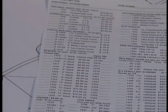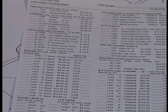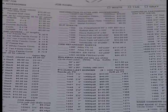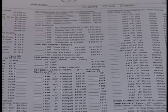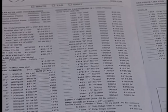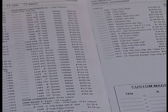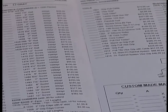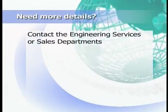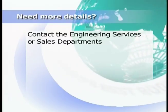The order blank also functions as your punch list. It addresses most situations that you will encounter on the rooftop during your survey, including two-way vents, stacks, drains, and accompanying CDR rings, tools, welders, fascia, drip edges, gravel stops, termination bar specifications, and other Duro-Last details, accessories, tools, and materials. Use this list to accurately record all details, quantity, and type of items that you will need. If you need more explanation or details, contact the Engineering Services or Sales Department.